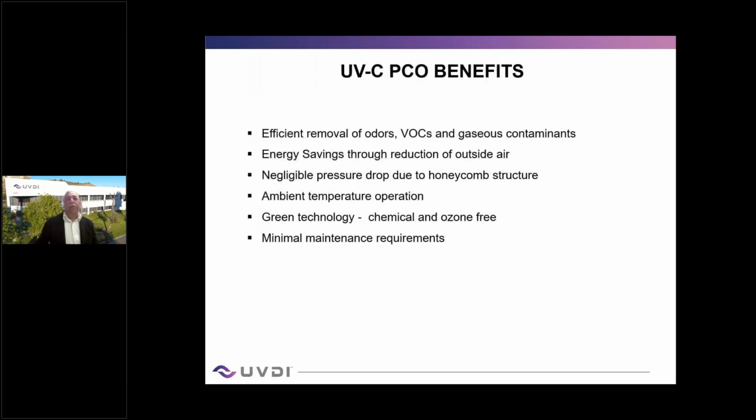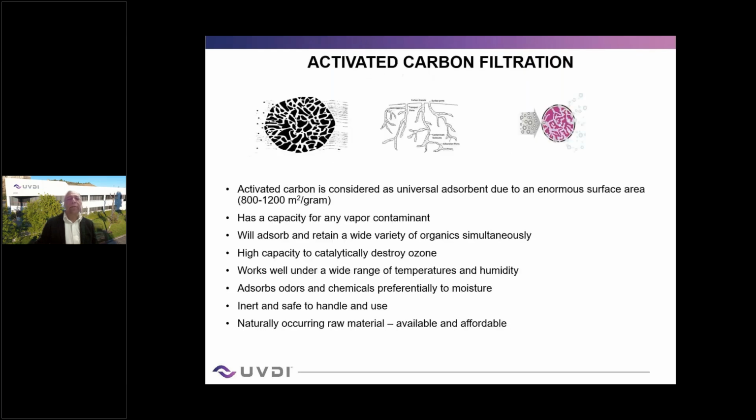So benefits of PCO: efficient removal of odors, VOCs, and gaseous contaminants. There are energy savings through reduction of outside air. If you're just bringing in outside air to remove your smell, then of course that's not advisable. Your energy consumption is going up. So you can add a PCO technology in your air handling system, which will remove your VOC and odors. Negligible pressure drop. The other advantage compared to your car catalytic process, this is ambient temperature. And of course, green technology, chemical and ozone free, minimal maintenance requirements.